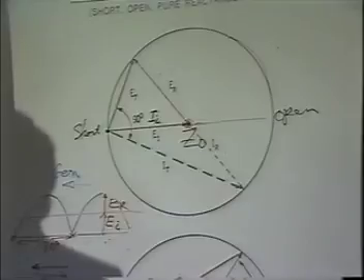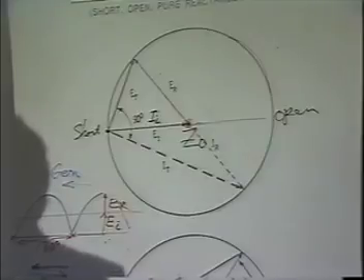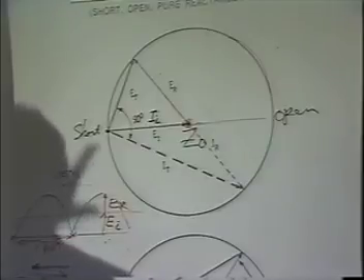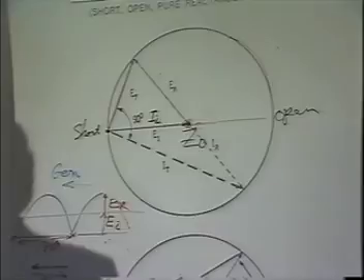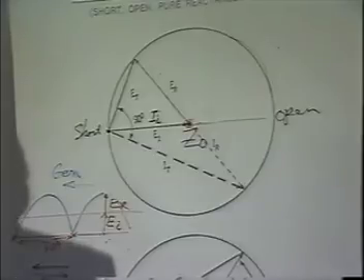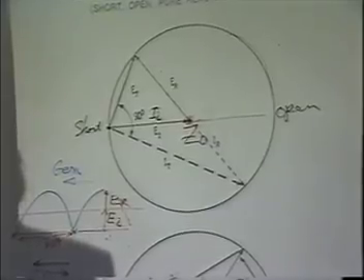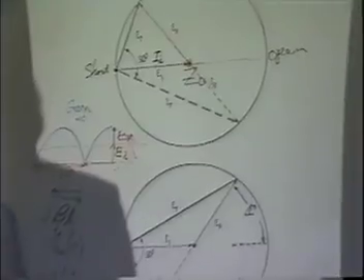Now isn't that what we said about a wave of voltage and current that left the generator, when we talked about the DC voltage throwing a switch and a wave traveled down the line? We said that the voltage and the current must travel together. And the incident wave going down the line, the incident wave and the reflected wave are in phase. That was defined, wasn't it?